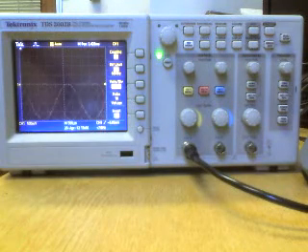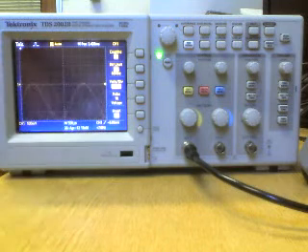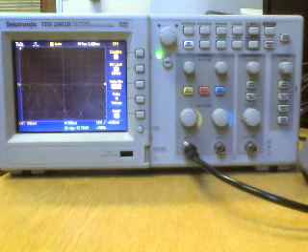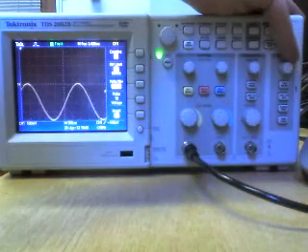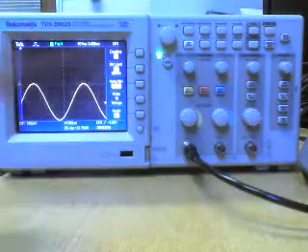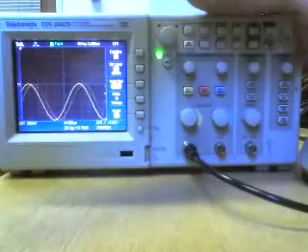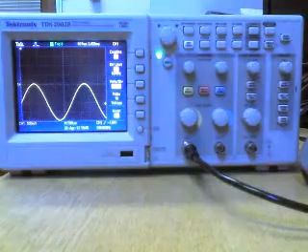As you can see, there's our waveform. It's scrolling across the screen just as much as the analog one was before we triggered it. Now we can change the trigger level and move it around the centre of the waveform. There it is, nice and triggered. So you can see our trigger level here. We knew it was above the waveform, so we just have to twist the knob until it is in the waveform, and there we are.